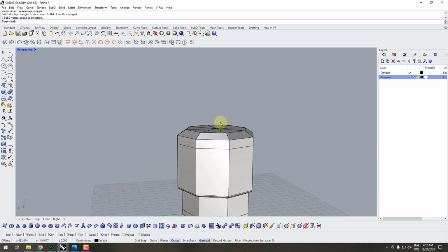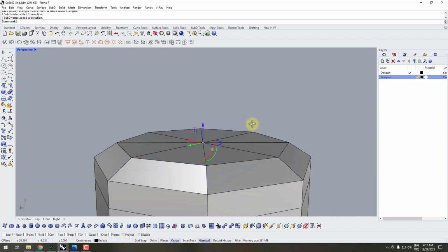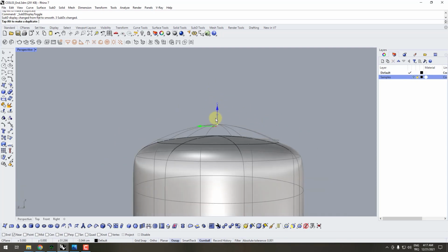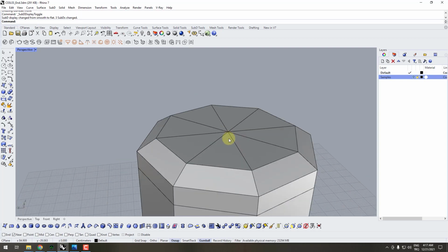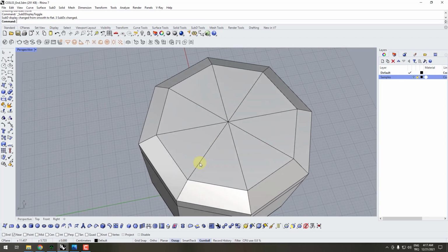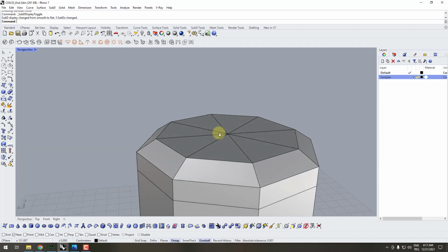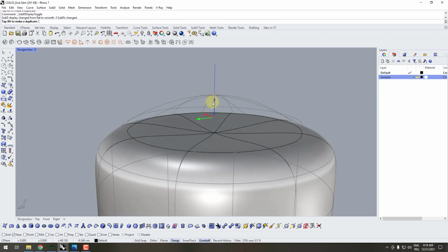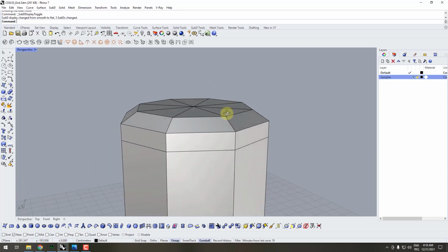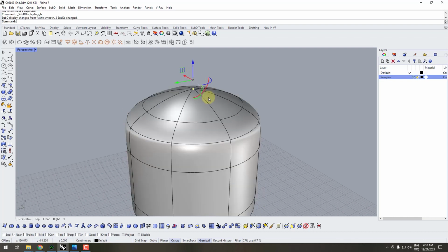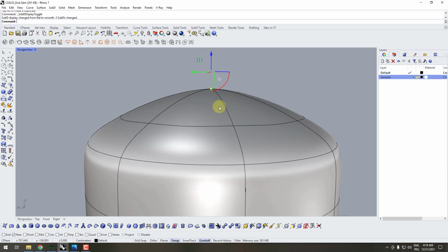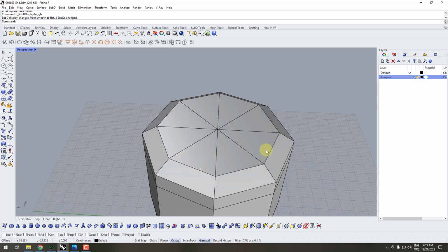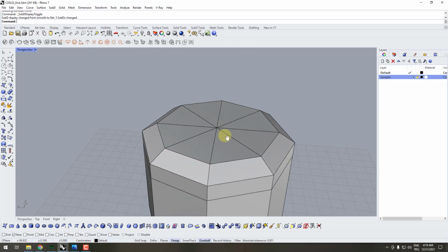For the puffiness of the upper side, I could just select the middle vertex and pull this vertex up, but this will not give me the same structure that I have accomplished by creating new segments inside of the outer edge and pulling all of them up. You can always make experiments with different SubD parts and evaluate the results. In this occasion, when I just pull this vertex up, it creates a more pointy geometry than I want, so I didn't choose to pull the middle vertex by itself. I prefer to create an inner loop and inner segments for my geometry.